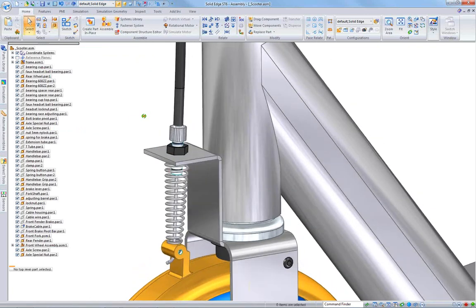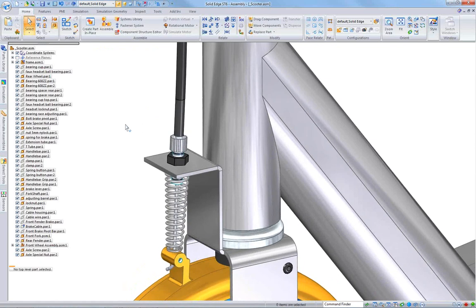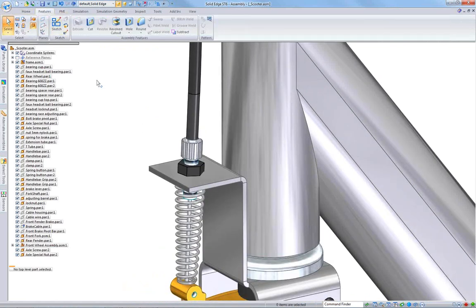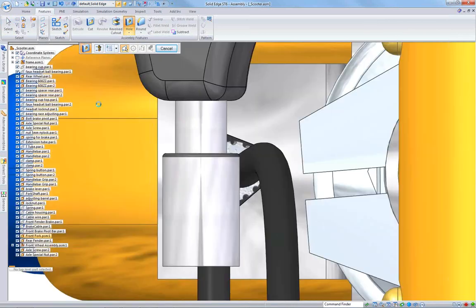And so there you can see that we were able to add those flanges very quickly. One last thing then is I want to add a hole. There's no hole in that flange because I just created it. And right from the assembly I can go into the hole command, and I want to pick this top face where I'm going to be placing the hole.